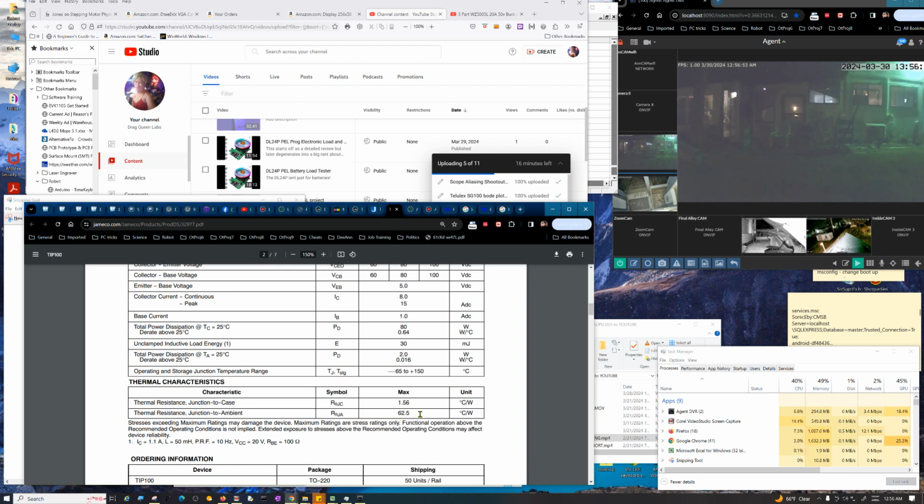Usually you don't use a heat sink with most op amps, but sometimes power dissipation in an op amp can actually be an issue. Even with a 741, there are cases when, if you're pulling full load on it, that thing can overheat. So you do still need to glance at these and consider it, at least in passing, if you're designing something you want reliable.